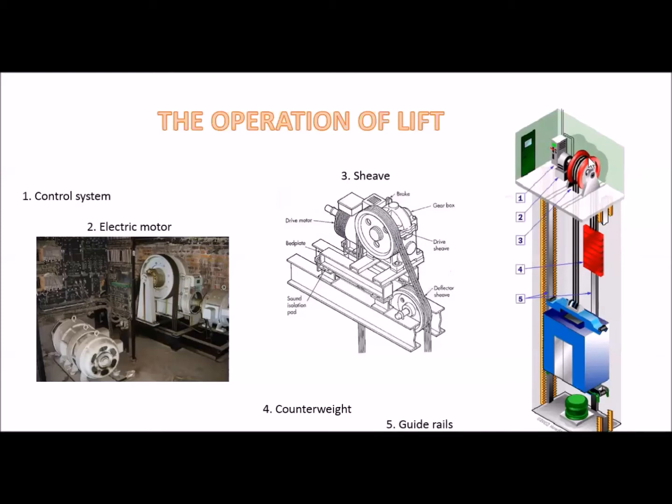The problem that we can face in the lift is if the motor loses a phase, it will cause the motor to lose some of its power and create an imbalance, which causes abnormal noises and vibrations. Besides that, the motor will pull more electrical current from the remaining phases and cause high temperatures when starting the motor. So it means that when the motor wants to start operating, it will take a high temperature.